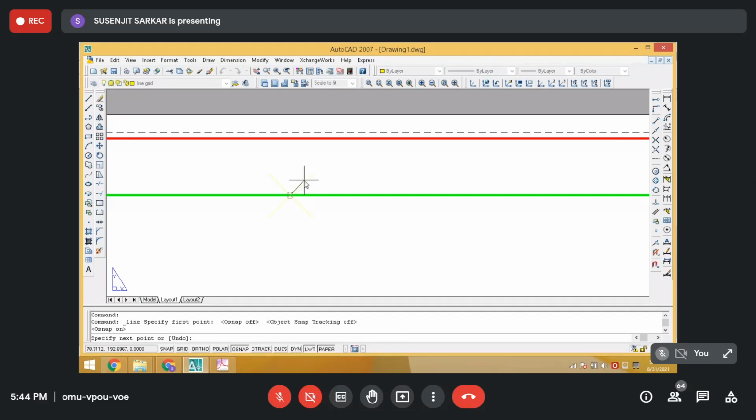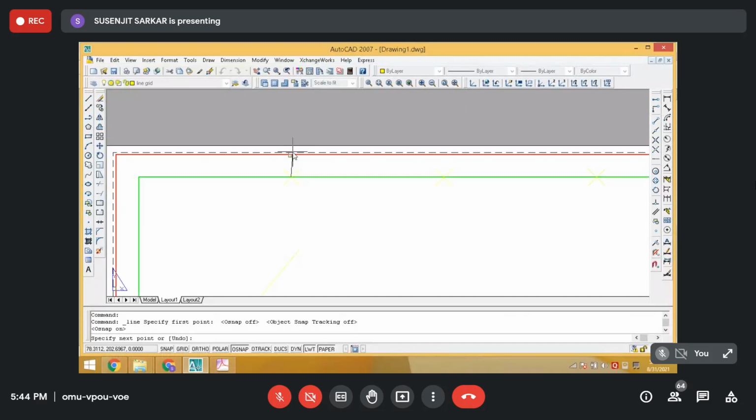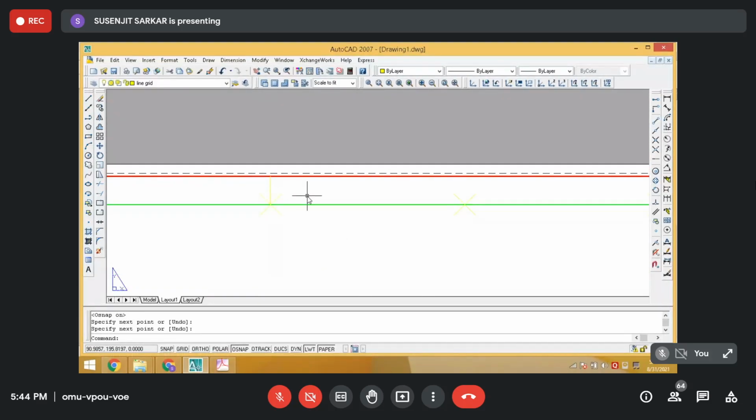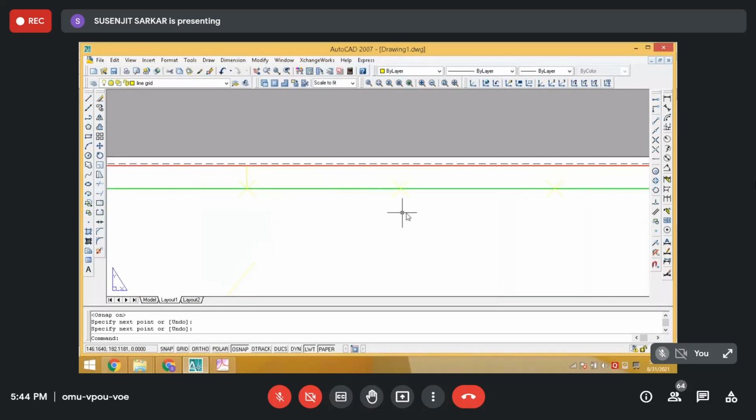This is a starting point. Now you can draw the lines. So vertical, perpendicular. See. So I've drawn the perpendicular line. I can draw it over here again. I click line command. I go to intersection. Then here, if I'm not getting the snap or track, click the track.